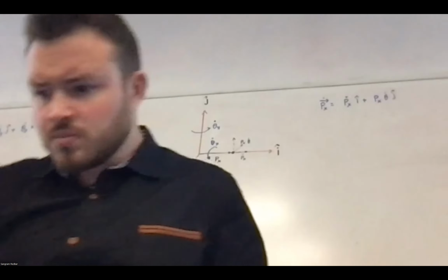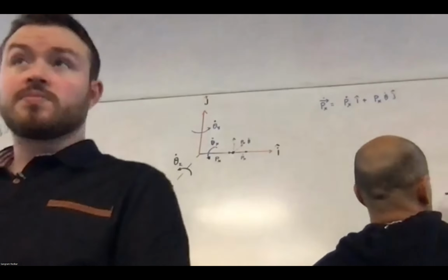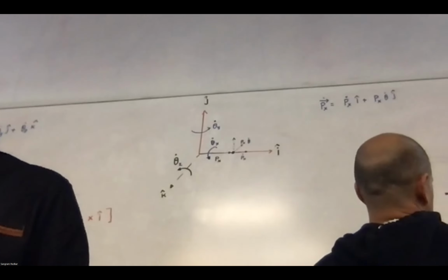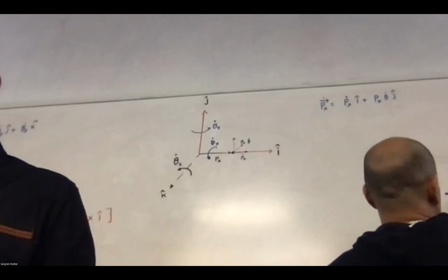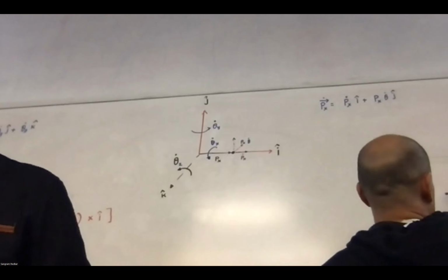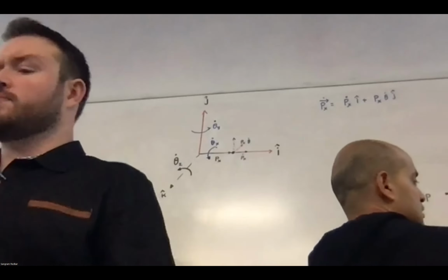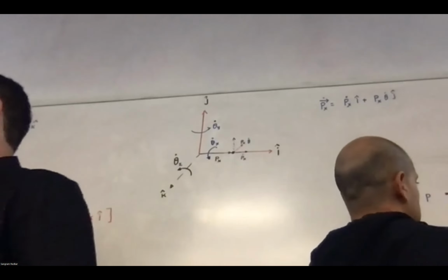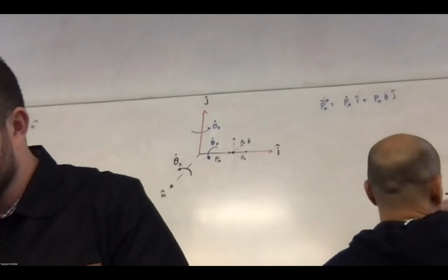So we just have a single equation, but how do two values of P work? You get a solution of P from the accelerometer, and you get a solution of P from the GPS. You can take a simple average. Okay, better accuracy than just one.